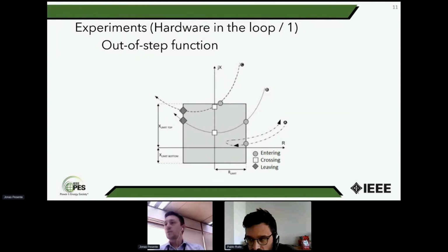It also allows counting the impedance trajectory entering the non-protective zone. It is important because, as we have considered many different disturbances, some stable dynamics can occur in a way that the electrical center does not develop inside the transmission line, which is the very common situation. So we had this particular situation that we can deal with using this type of protection feature.